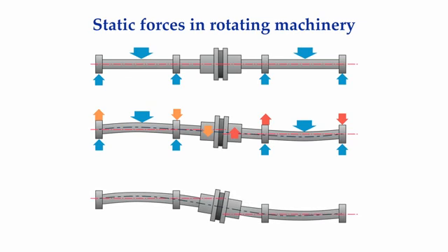If we continue to misalign these two shafts, the shafts begin elastically bending even more. The gravitational loads are still present across the coupling. The downward force on the end of the left shaft has increased, as well as the reactionary forces on its bearings, and the upward force on the shaft on the right has increased, as well as the reactionary forces on its bearings.